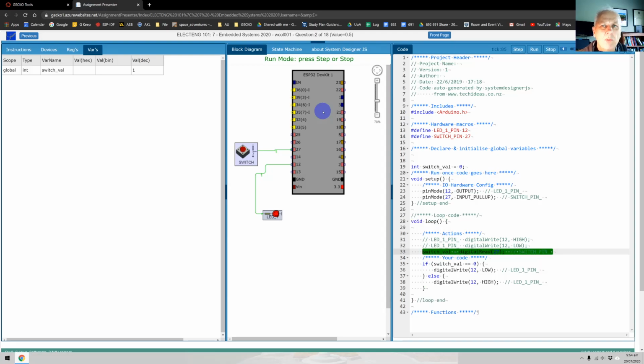So you're aware that this takes a certain defined amount of time to happen. I've slowed this right down, so this is going to take quite a while. I'm going to press that switch again now, and the value of the switch goes 0, but the value in the variable does not change until it actually reads the switch input pin again.